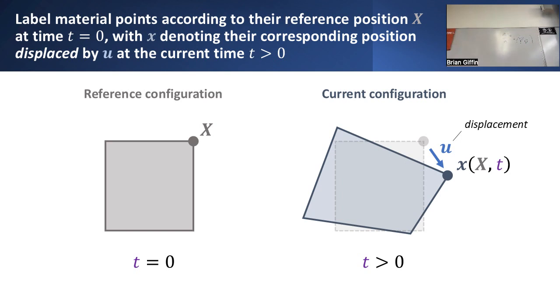So what was its initial position? And at what later time am I examining its new position? In effect, I can characterize the dependence of this particular new displaced position in the so-called current configuration, or deformed configuration, of this block of material by saying that deformed positions of points which had some original coordinate, capital X, will deform into this new position at some later time, t. And it'll certainly vary as a function of time.